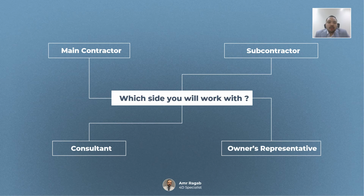We are here. For a subcontractor, as an example, BIM is mainly about detailed planning and coordination. They use 4D to visualize their own scope of work. So, as an example, if you are a subcontractor for steel erection or facade installation or MEP sequencing, this helps them see exactly when and where they fit in the master plan and how their work interacts with other disciplines. So it's all about improving coordination, logistics, and site productivity. So 4D helps subcontractors turn their weekly look-ahead plans into a clear visual.